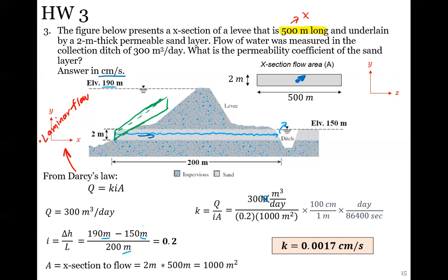So generally laminar flow means slow velocities. So if we had a super, super high velocity here, then there must be some mistake somewhere. Like if we had something in the 1,000 centimeters per second range, just think about that. That's pretty fast. So this value being really small, you could probably take a ruler and count out the centimeters and picture the water traveling very, very slowly through that. So these numbers should always be small. So double check that.